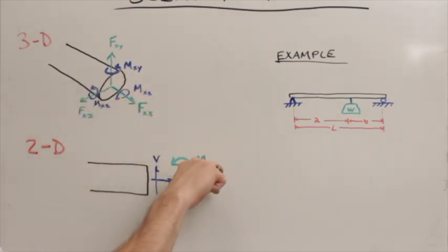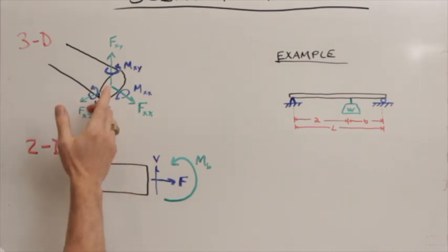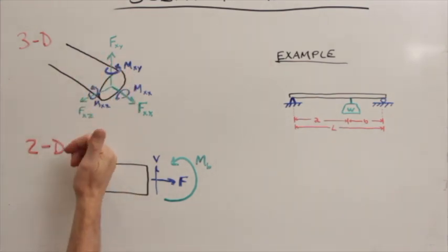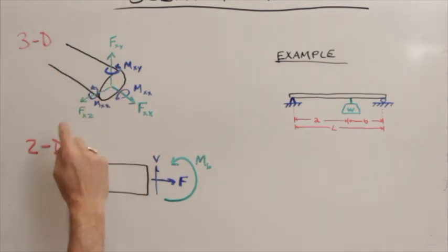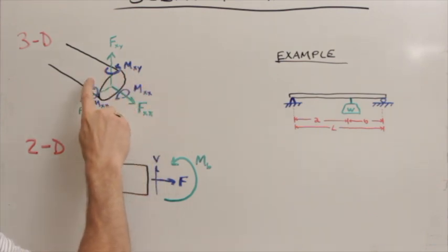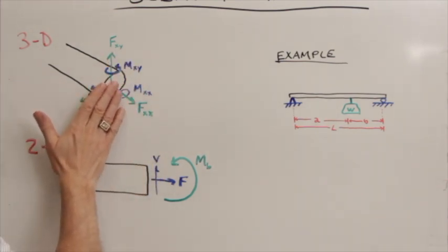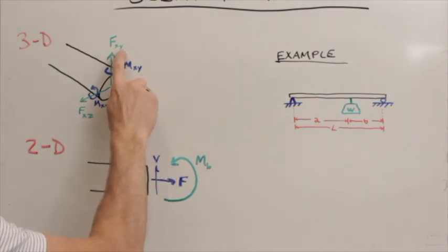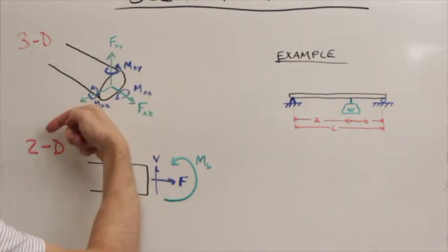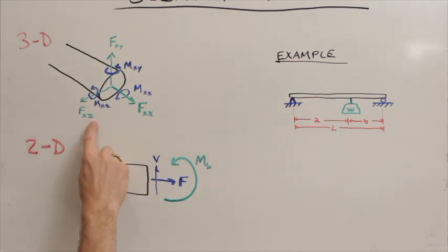And here the face is in the X direction because the normal to the face is in the X direction. So for this slender member at the end, the first subscripts are all X's because this end face is perpendicular to the X direction. Then the second subscript denotes the direction that the force is acting, Fxx here. Y is up, so that's Fxy. Z is this way, so it's force Fxz. Again, the force on the X face acting in the Z direction.